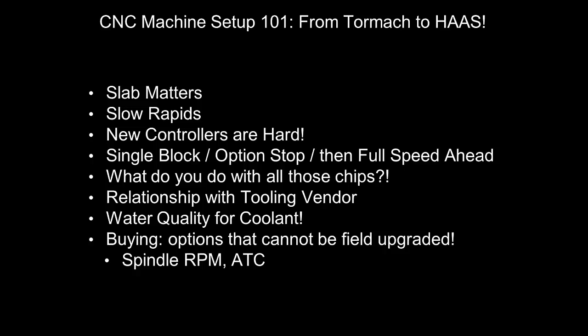Slow rapids. So slow down your rapids. Some of this stuff kind of jumps around, but the first thing I did when I started running the machine, since modern machines go 800 or 1500 inches per minute, was just park the thing on 25% rapids, because I don't need to be going 100%, and I really didn't want to crash that machine.